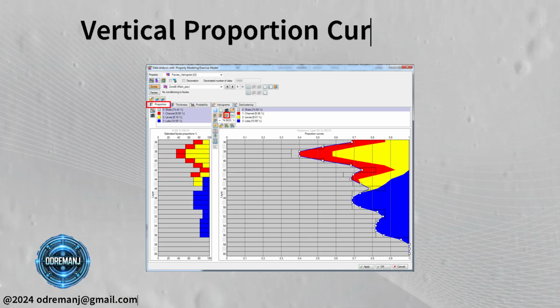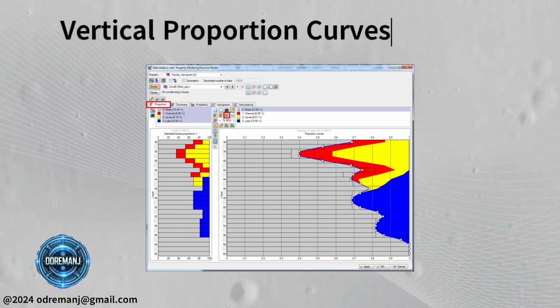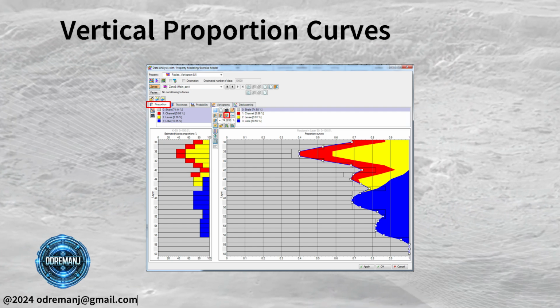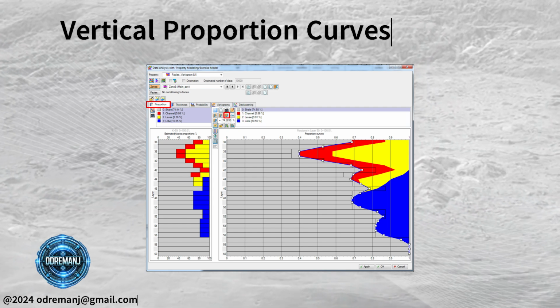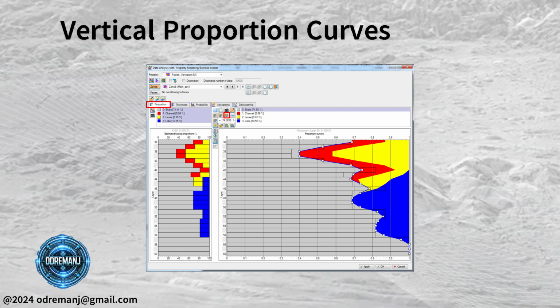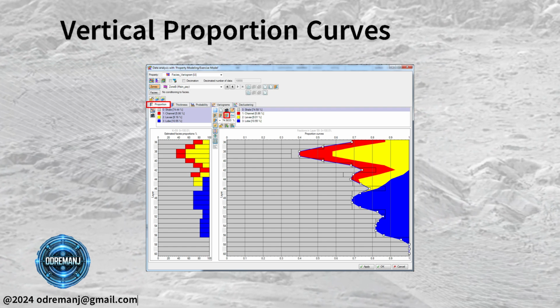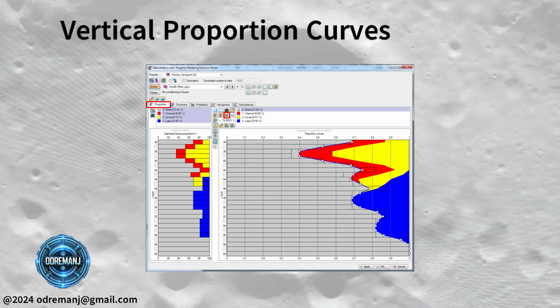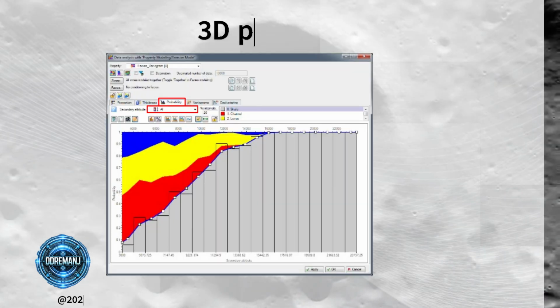The image shows the vertical proportion method in Petrel, used to analyze and adjust the probability distribution of facies in a selected zone, based on the K-layer fractions. The process controls the vertical facies distribution during modeling. The user can edit facies fractions when they don't reflect the expected 3D population. In this example, channel and levee facies are more abundant in the upper layers, while lobe facies dominate the lower layers. Variogram ranges, trends, and probability.